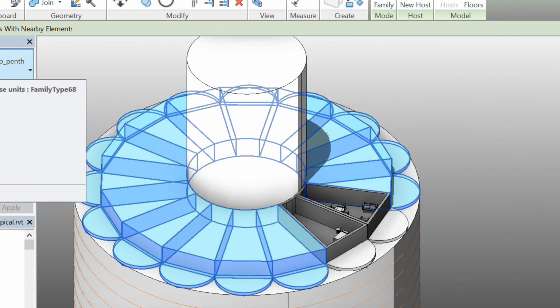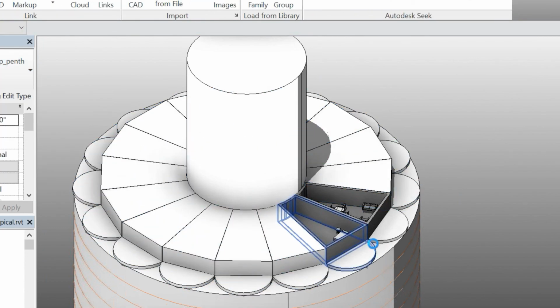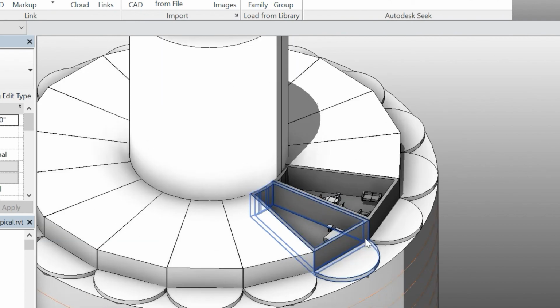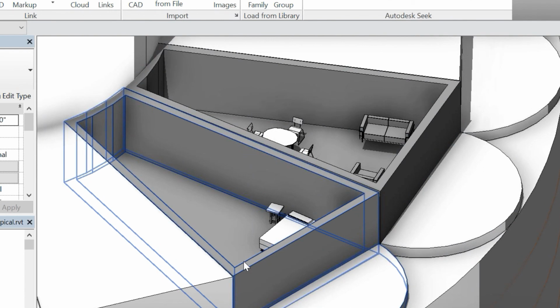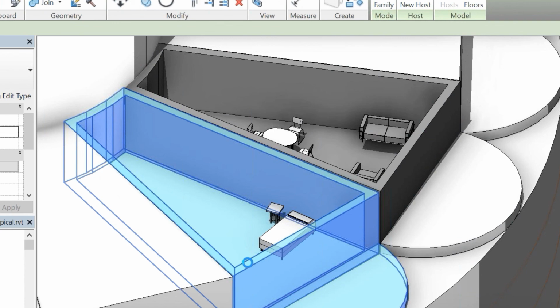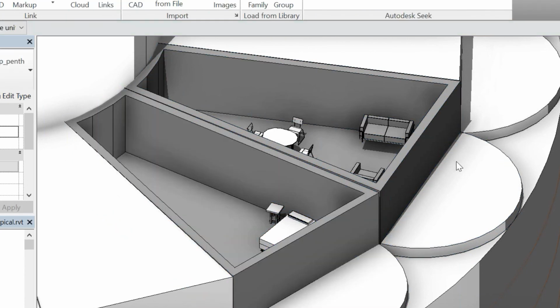Now these darker gray areas, this is stuff that, because I did that shelling operation and pushed that floor down and not all the way through, Revit can't create a conceptual mass from this. So you're going to get an imported set of geometry, which is fine. It's just a reference, but just to be clear, that's how things get segmented. So you can still use this as a reference.